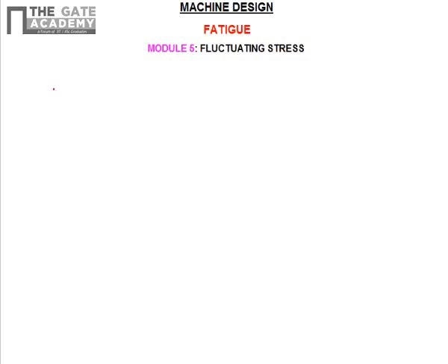In the case of a ductile material, we have seen that when the stress levels are very high, as in the case of a notch where we have a concentration of stress near the notch, local notch yielding takes place, which results in strain hardening of the material.